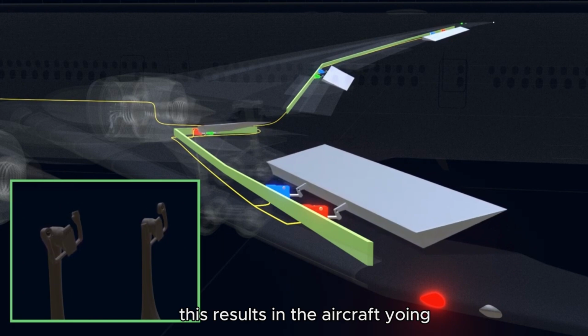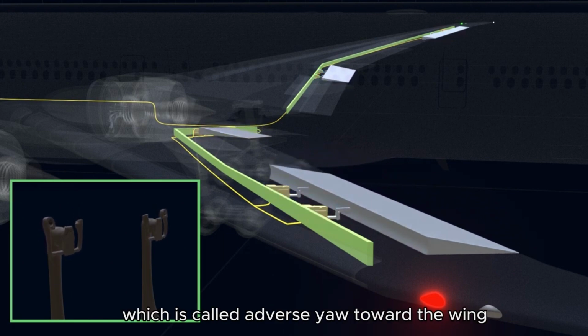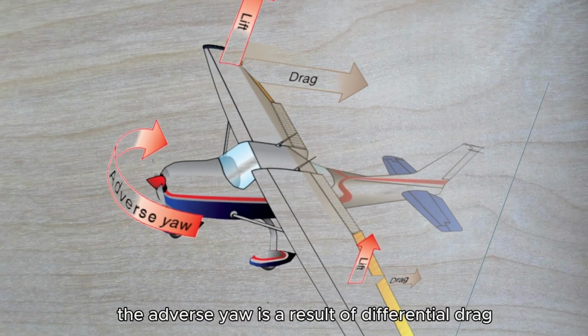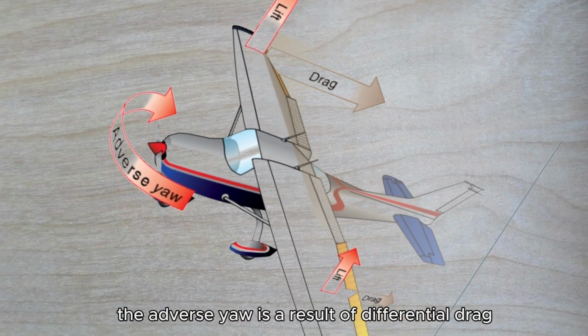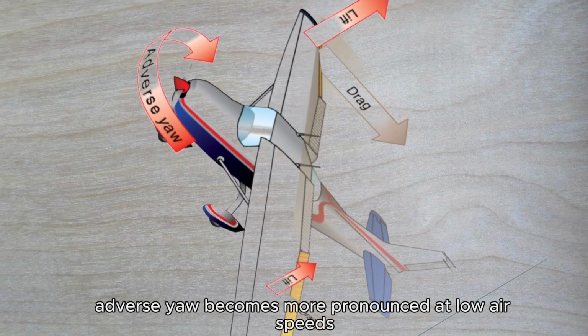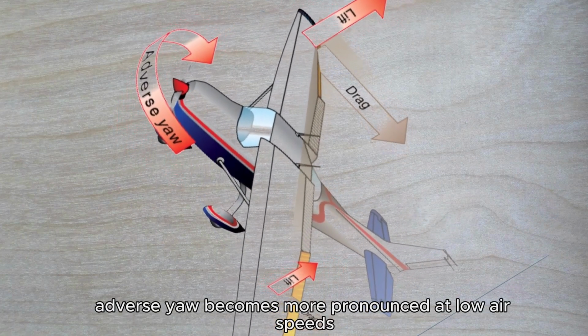This results in the aircraft yawing, which is called adverse yaw, toward the wing which had experienced an increase in lift and drag. The adverse yaw is a result of differential drag and the slight difference in the velocity of the left and right wings. Adverse yaw becomes more pronounced at low airspeeds.